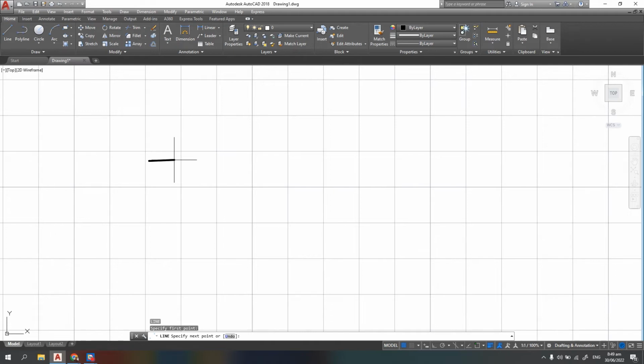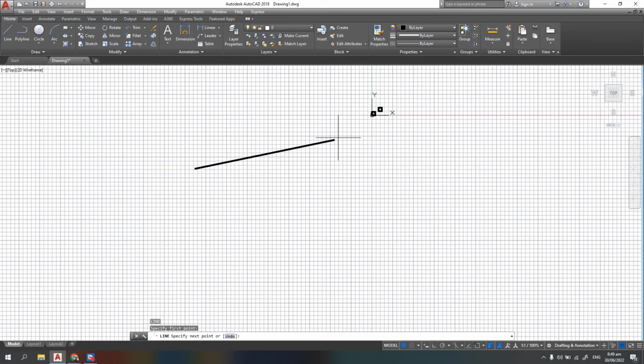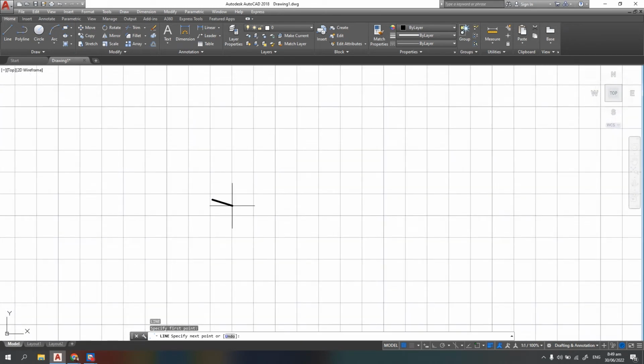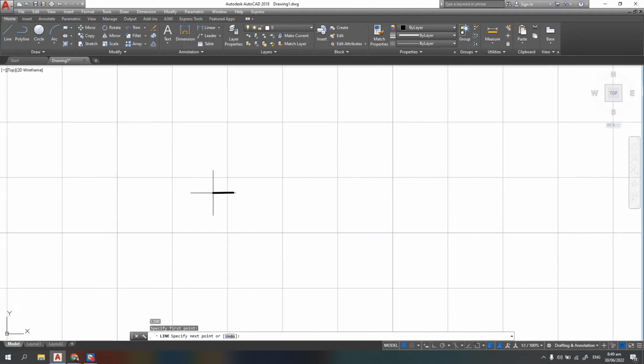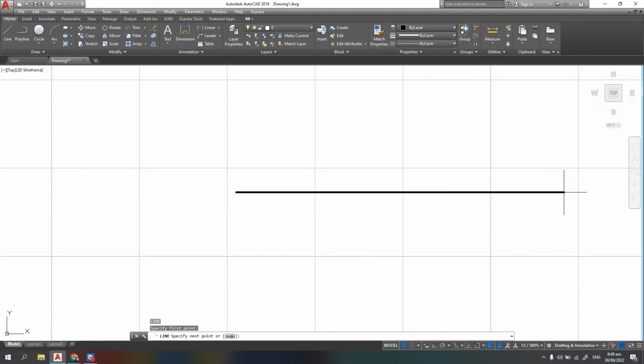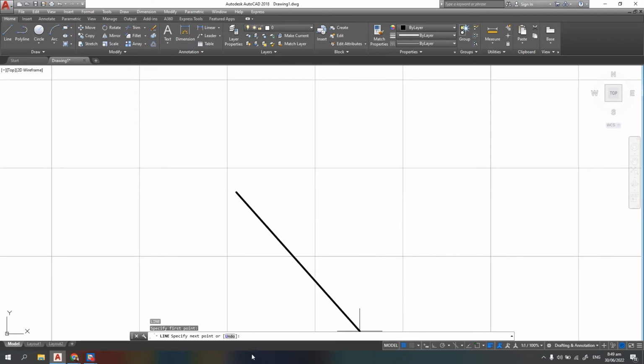It is not actually the real 0, 0. That is because this is your actual 0, 0. But in using the relative coordinate entry, we can assume relatively that this is your origin. If this is your origin, we can say that this point is also your 4, 0. Right? But doing that here at your command line, all you need to do is use @. That is the symbol for relative. Removing that will shift you back to absolute.